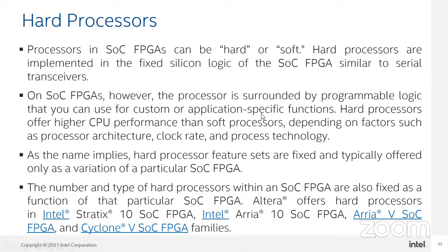Now, can we call all FPGAs SoC FPGAs? No, because the MAX 10 device which we were discussing has only the soft core processor. So what are SoC FPGAs? Those with a hardcore processor immersed in them. That means you have the Cyclone V SoC FPGA, Arria V SoC FPGA, and Intel Arria 10 SoC FPGA. These SoC FPGAs have a dual core ARM Cortex-A9 immersed inside the FPGA fabric, whereas the Stratix 10 and Agilex devices, the high-end devices, use the quad core application processor A53 immersed inside the FPGA fabric. That's what I explained.